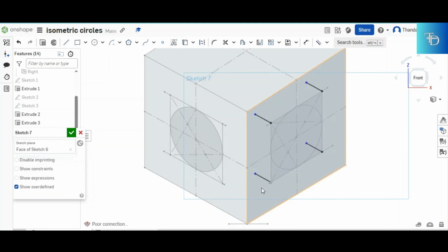Now after extending all your corners, you go ahead and join all the four corners so that you can come up with what? With a second square. But now notice how the second square is going inside the box. It's going inside the cube now, which is exactly what we need because the hole is going inside. First one right there, the second one right there, the third right there, and then finally the fourth.